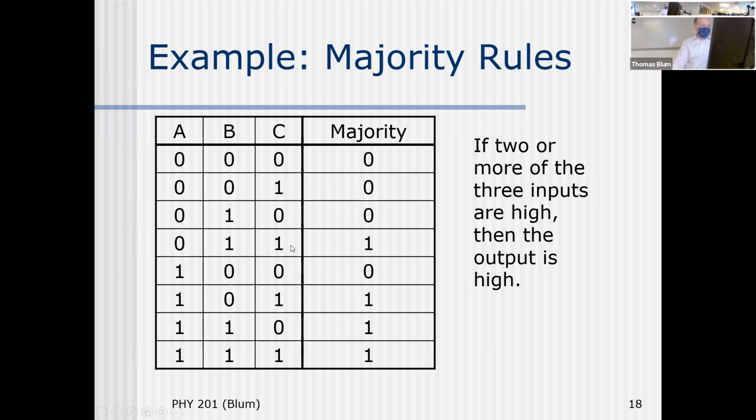So if we're there, A 0, B 1, C 1, that expression would be, again, I'm going to try to make 1s out of everything. So it'll be A prime B C. Right? A prime B C. So if A is 0, but I prime it, then A prime is a 1, and then I would have 1 and 1 and 1, and that AND gate would produce a 1 in that row.